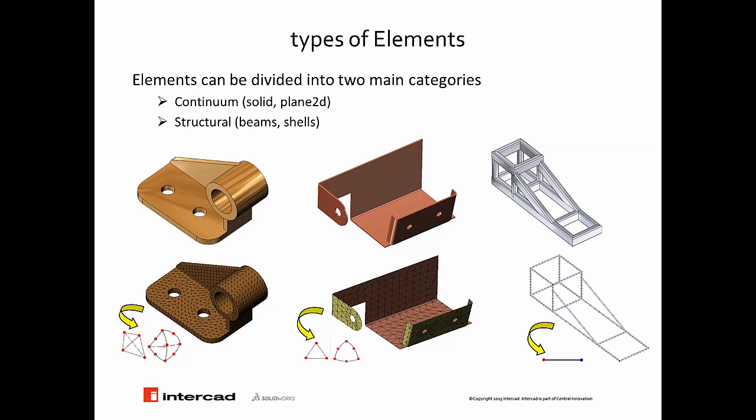From the theory, we can prove that if you are putting a series of 2D elements, either high quality or low quality, and looking at the top or bottom face, result, stress, strain, or anything else could be propagated through the thickness, and looking at the other aspects of the stress, like membrane, like top face, bottom face, and etc. That could be again extended to a new area, where if you have a structural, let's say, series of members added together and creating a frame like that, looking at the cross-section, dimensions of a cross-section is much smaller than the extrusion lengths.